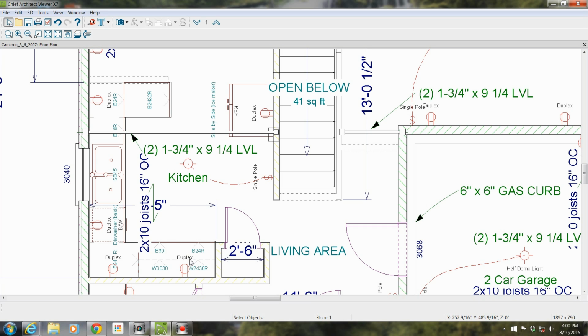you'll see that this B stands for base cabinet. So this base cabinet right here is a base 24 inches. And this one is a wall 24. And the base cabinets are standard height. That's why there's not a double number. For the wall cabinet, it's a 24 and a 30-inch high. You could have 36, 42, 48 tall. And then here you've got a wall 30, 30. I said that base already.